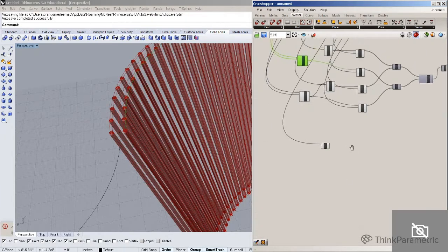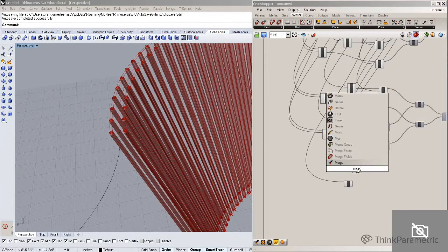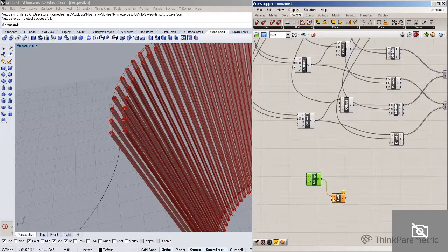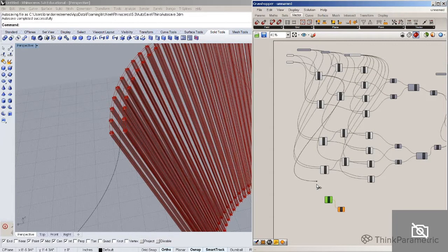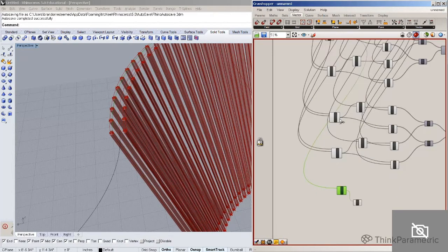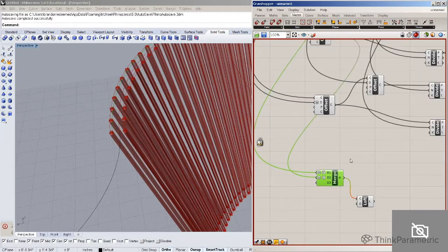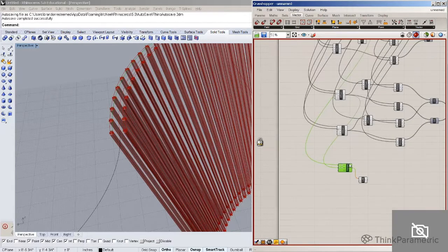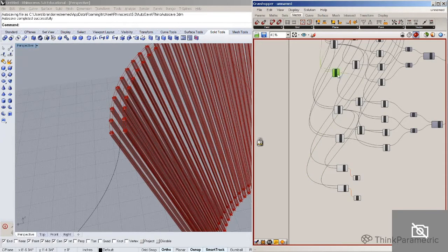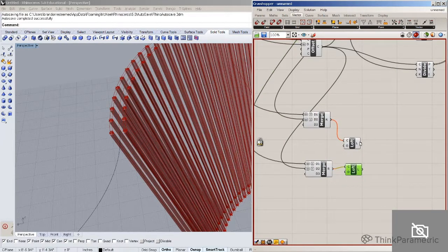And this also, of course, is one of the things that we're going to merge to get. So merging is very necessary to loft to clean up the data form. So that's from the first outer, and we're going to turn off the solver because we have to do the cleanup again. And graft and simplify, graft and simplify. And we're going to do the same operations for the bottom, and we'll do that. Replace that one. We're lofting the top and the bottom